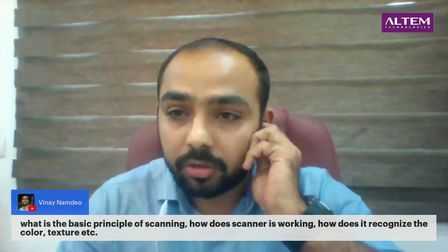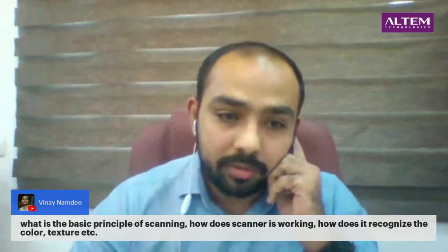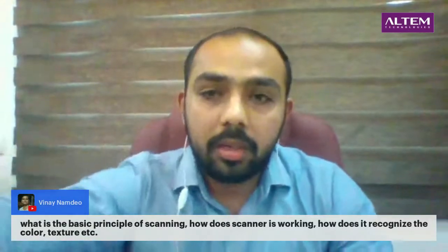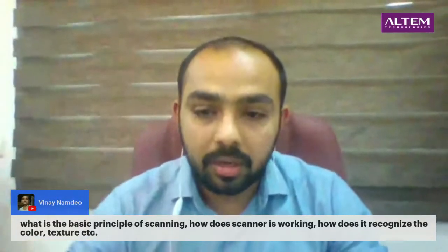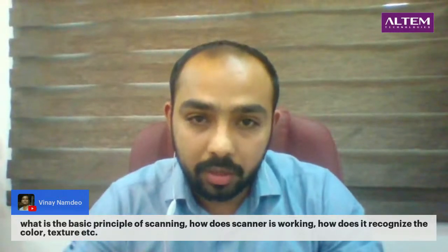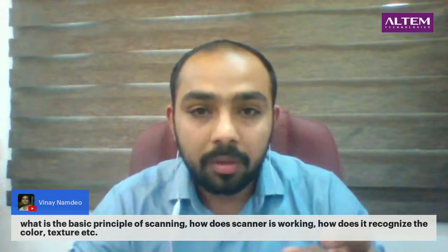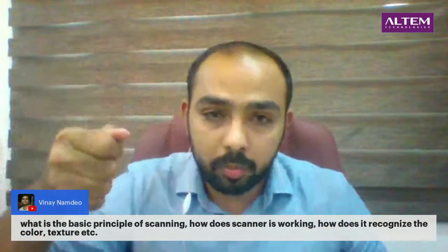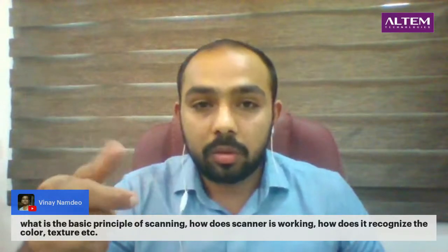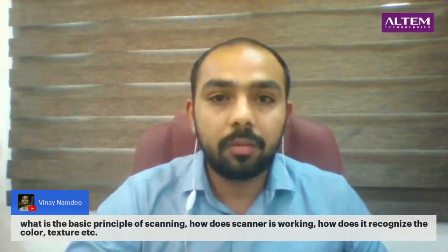I have seen a question: what do you mean by resolution of a scanner? Basically, 3D resolution means differentiating between features. If you are capturing data that has small features, of below 10 mm or 2 mm, and you scan those portions with a bigger scanner, then the scanner, like the Eva, offers a 3D resolution of 0.2 mm, meaning 200 micron. Below that, it will not recognize.